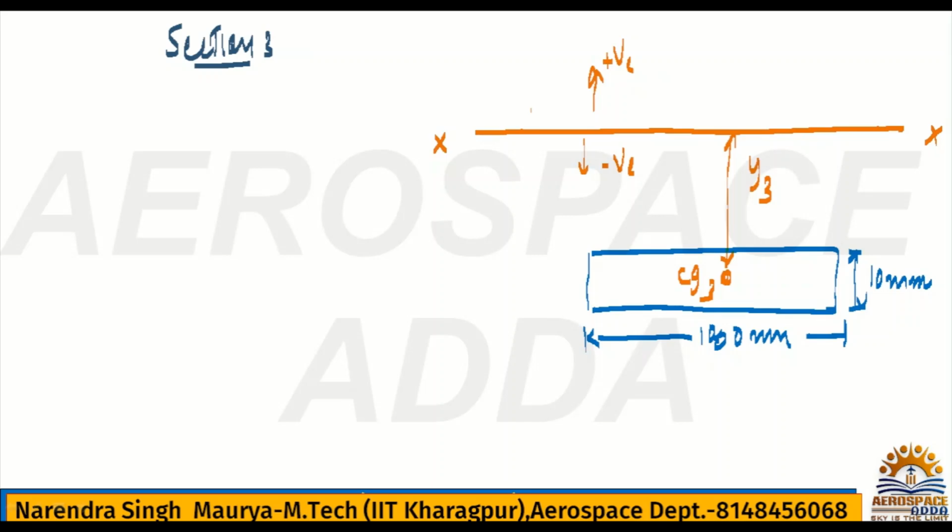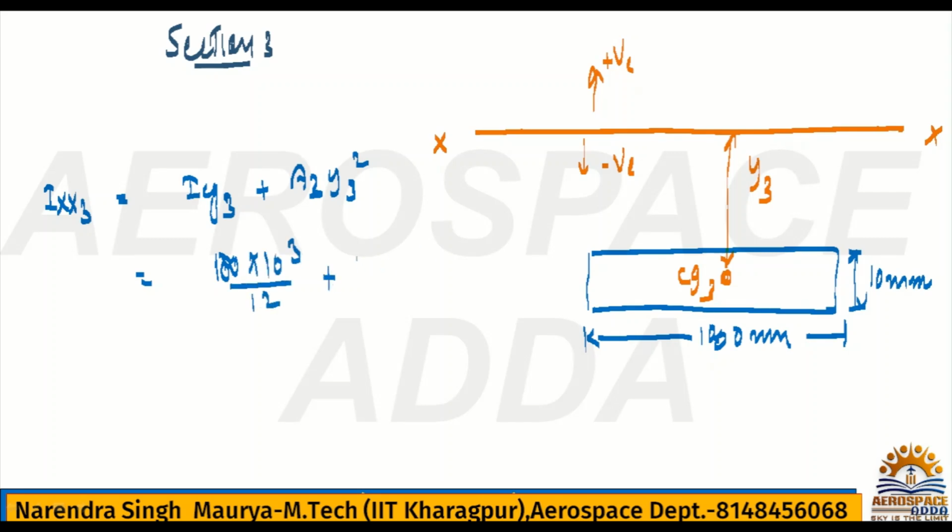Okay, now if you calculate Ixx3, then it's nothing but ICG3 plus A3 Y3 square, right? What is the ICG3? If you check, it's nothing but 180 into 10 cube by 12 plus area, which is 1800 into Y3.